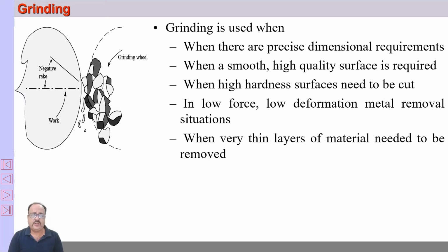So most important, in general, grinding is used when you want to remove a very small amount of material and give it a very good finish and obtain a high accuracy of the workpiece. Normally other machining processes remove the maximum volume of material and then it is finally finished by the grinding processes. However, in modern grinding technology, grinding is also used for removing a large volume of material by a process called creep feed grinding. We'll be discussing creep feed grinding later on in the next lecture.